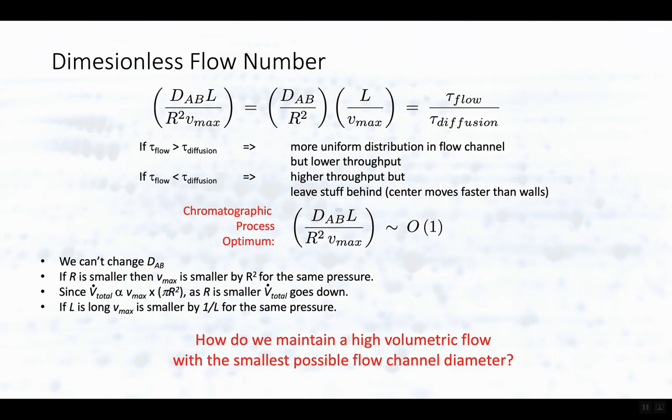If we just multiplied a number of those smaller pipes together, welded them together into a big group, we could up our volumetric flow rate by the number of pipes we put in parallel. That would be great, except R would have to be absolutely the same in each pipe in order for the flow rate to be the same through those pipes.